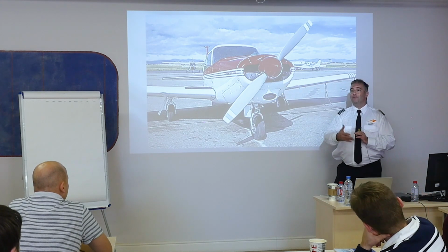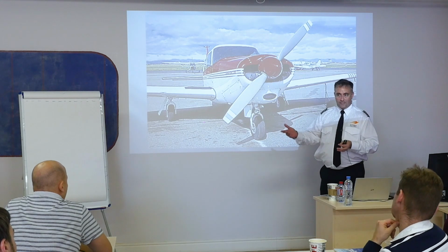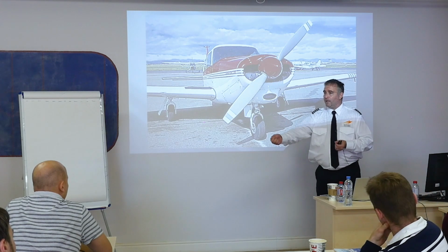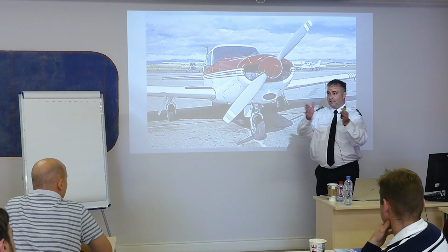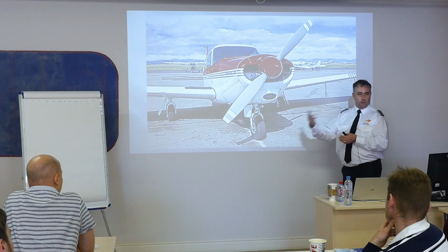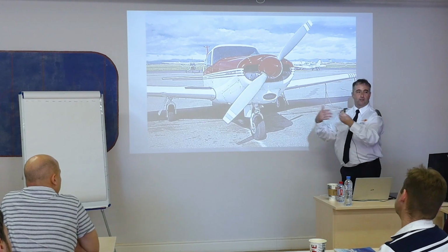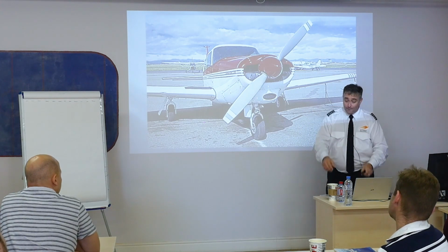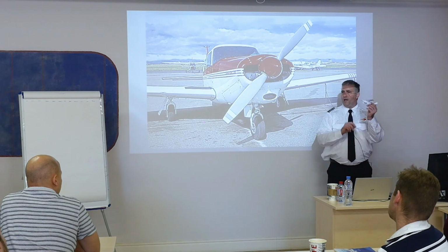So, if I'm going to make a before takeoff checklist, which I do every time, and I advance my throttle and check the engine and make sure it works, point that airplane into the wind so I get the maximum amount of airflow. Right? We're on the ground, at a moderate power setting, point it into the wind, allow maximum airflow. If I'm taking off and climbing, use a cruise climb.